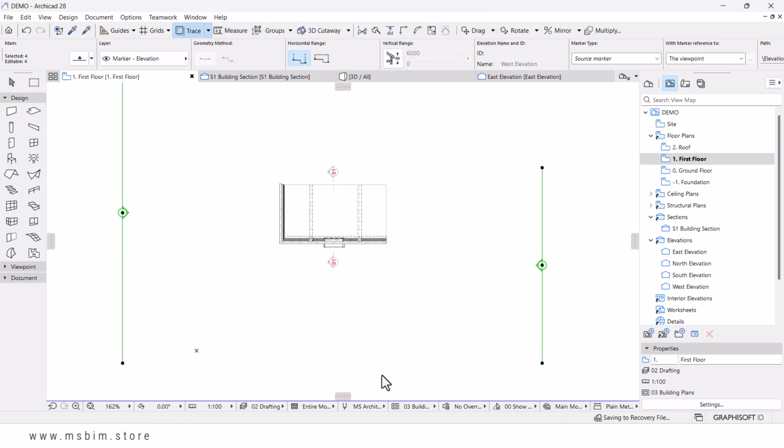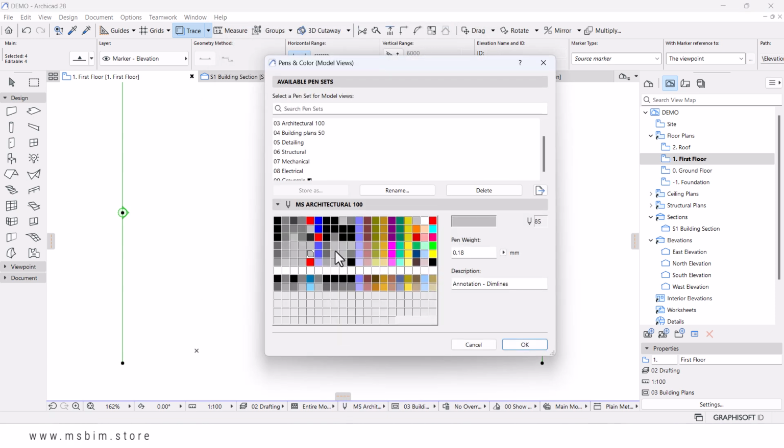Okay, I'm going to go back and adjust my pencils. I'm not going to override within the element settings, because I'm thinking for the future. If you want to develop a template, this is how you do it. You set the pens that can be implemented across all the project. If you've used default pens, it will pick it up because you are using the structure of your ArchiCAD.